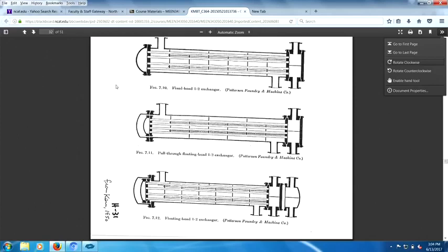Oh, when I was an undergrad, we had a heat exchanger. It was pretty funny as hell. It had these baffles in there. And what happened is the baffles were so bad, we injected dye into the shell side fluid, to see what would happen. It's a visual glass shell. And we injected the dye, and the dye went right through. It didn't go across like that. It didn't do that at all. That's because the baffles were poorly designed. There was a lot of leakage in there, baffle leakage. In other words, flow bypassed the baffles. In other words, it'd go through here, go around the tubes. That's not good.